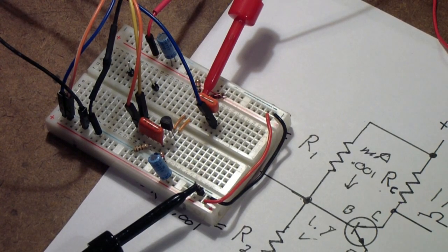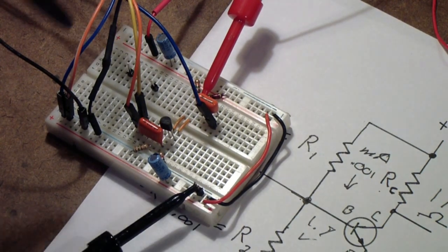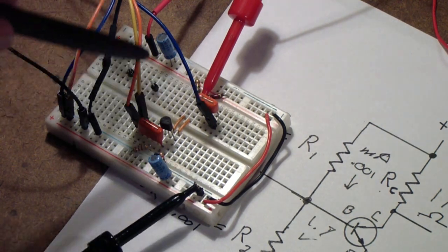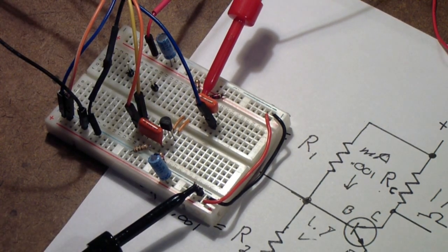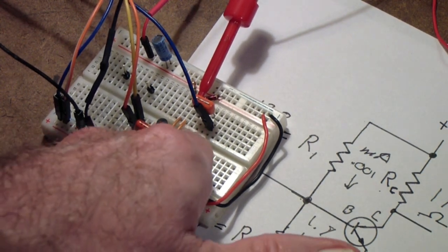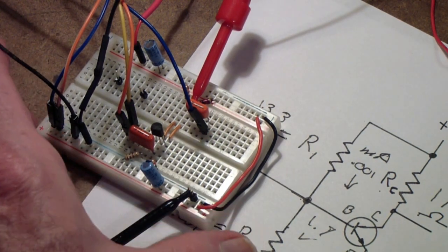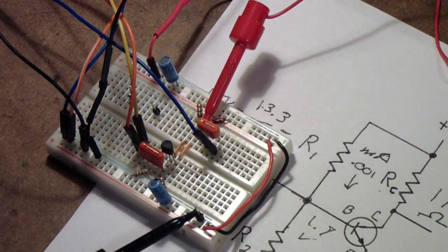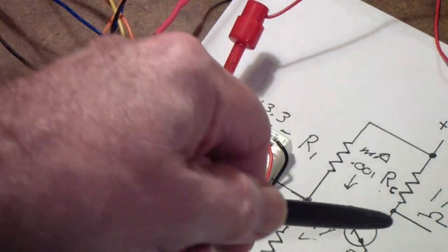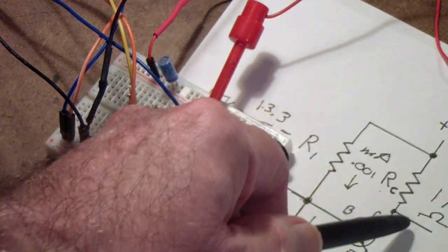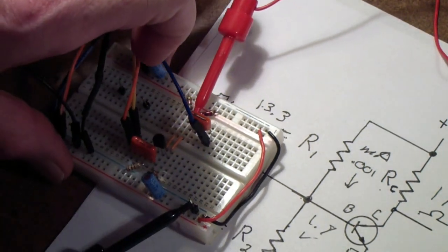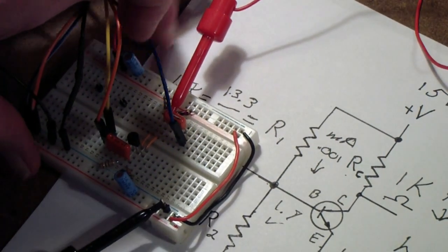I put together the circuit on this breadboard, and don't worry about all the extra parts on here. The only extra parts are these capacitors here, here, here, and one up there. I'll talk about those a little bit later. The transistor is right in there behind that capacitor. Turn this so you can see it a little better. But what we're interested in is we determined that there was going to be about 10 volts across this resistor, and we'd like to know whether that turned out to be true in our circuit.